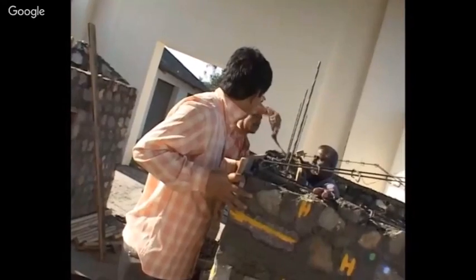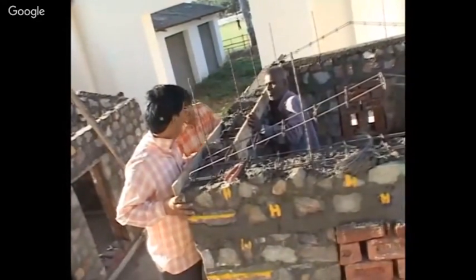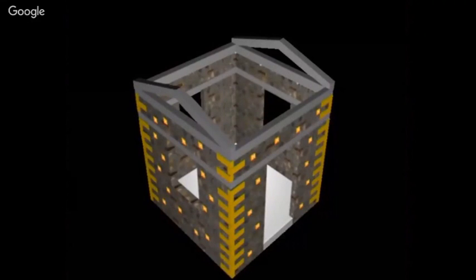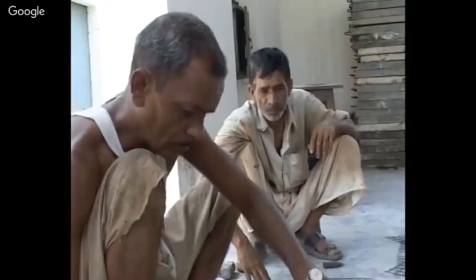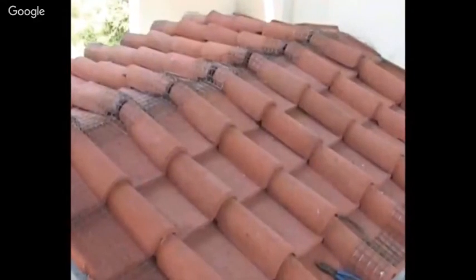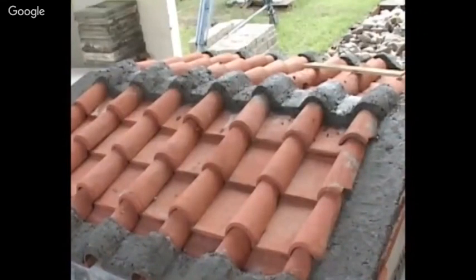In the stone buildings, another horizontal seismic band of the same dimension as the lintel band is provided on all four walls at the eaves level, and a gable band is extended up from this band. In the earthquake-resistant masonry model, wooden trusses and cross bracings are used instead of the usual rafter system in the roof. In order to prevent sliding of the roof tiles, they are bound with wire mesh at the ridge and the edges, and concreting is done on this mesh.